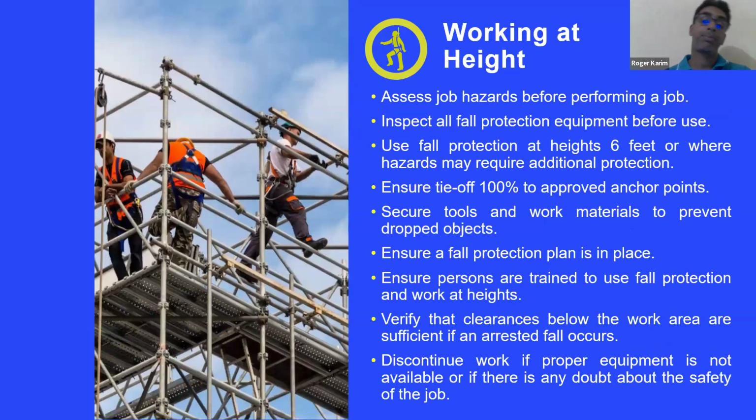Work at height: ensuring that your scaffolding is properly erected and certified by a competent person, and persons are wearing their fall protection.